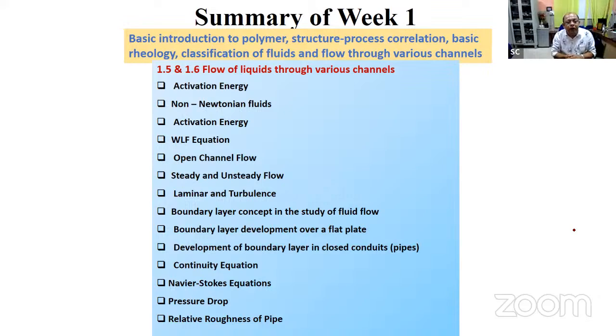Okay. So, again, you can depict the flow by the Arrhenius equation, say, for example, okay? So you all know the Arrhenius equation goes through an activation energy barrier, essentially, okay? State 1 to state 2, and that free energy difference between this initial state and the intermediate state or transition state, you call it activation energy. Okay? And then you have non-Newtonian fluids, and then its activation energy. I talked about the WLF equation, Williams-Landel-Ferry equation, which is pretty much based on the free volume theory, basically, and Doolittle's law that I elaborated.